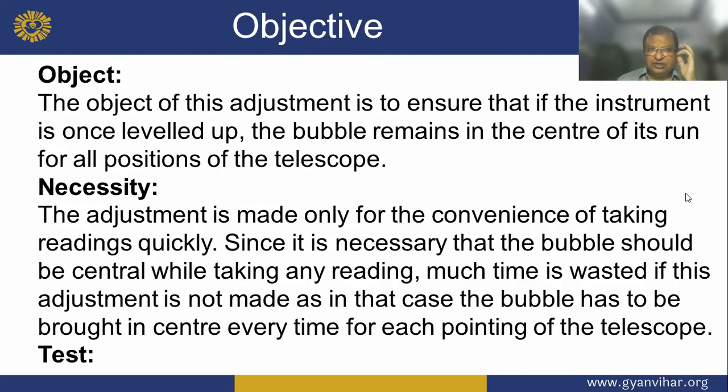Now the object of adjustment is to ensure that once the instrument is leveled up, the bubble remains in the center of its run for all positions of the telescope.